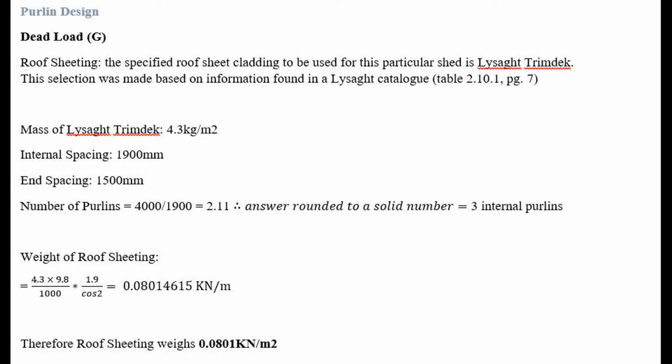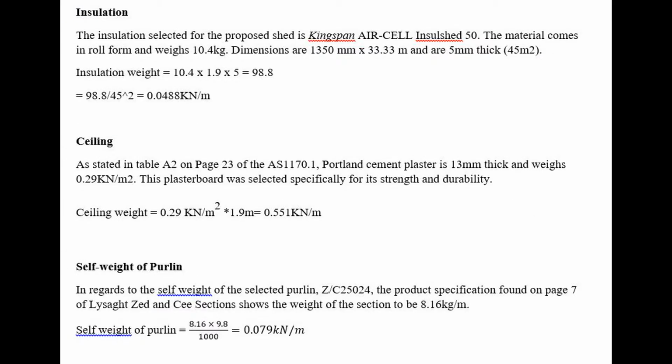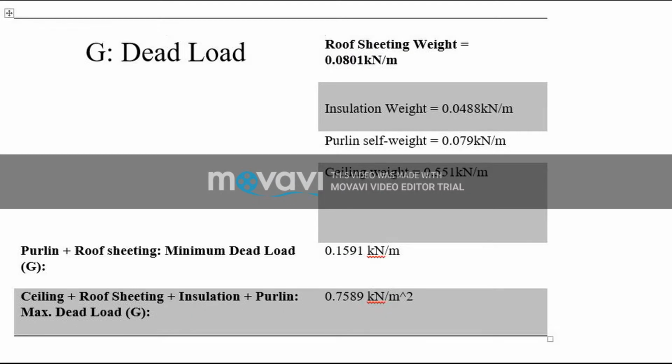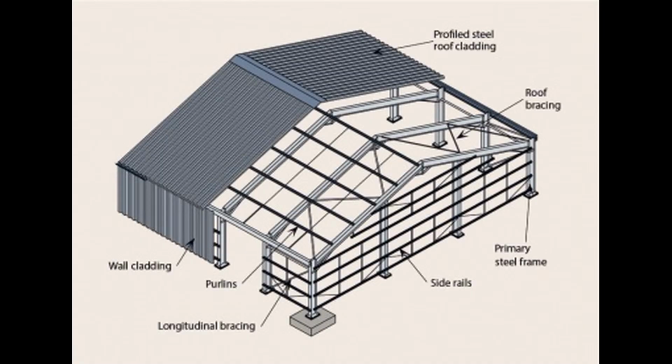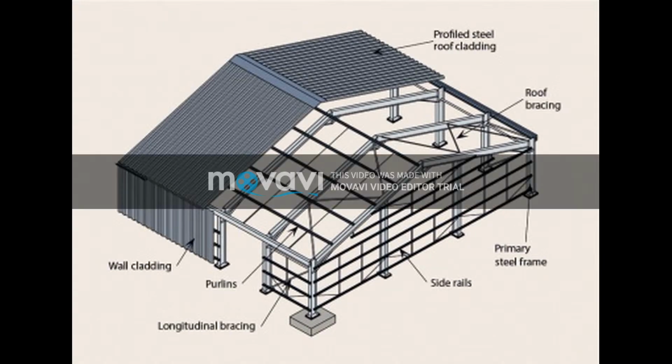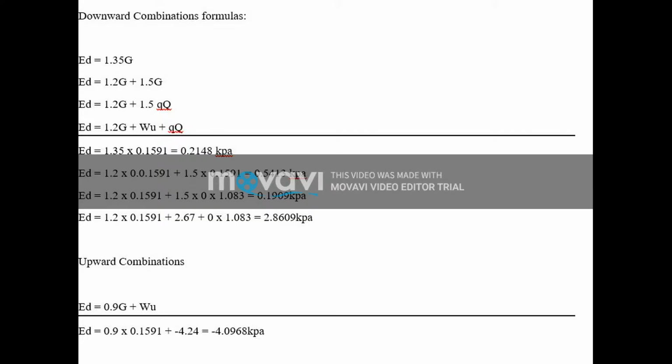Second of all, the purlin and girt design was constructed. For the purlin design, we begin with calculating the dead loads of our roof members. Roof members consist of the sheeting, purlin self-weight, ceiling, insulation and service weight, for example ducting. Other factors that were considered were the pitch of the roof, which was only 2 degrees for us, also the mass, the price, limitation supports, and the total dead load.